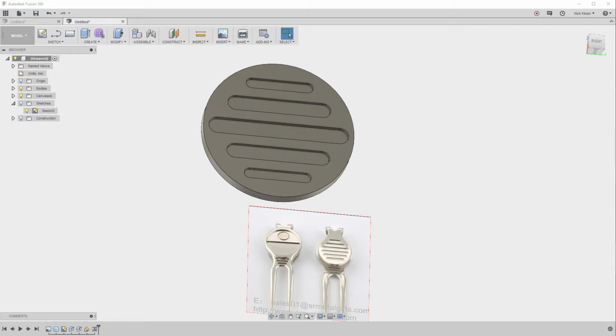It kind of printed up, but there were breaks in the bone, so there was all the support material that was needed, and it was a super pain to remove in any other way with normal material, because you have to get in there and dig it out. With soluble support material, I printed it upside down, and I was just able to rip off the soluble support material, so a lot of it very easily separated.